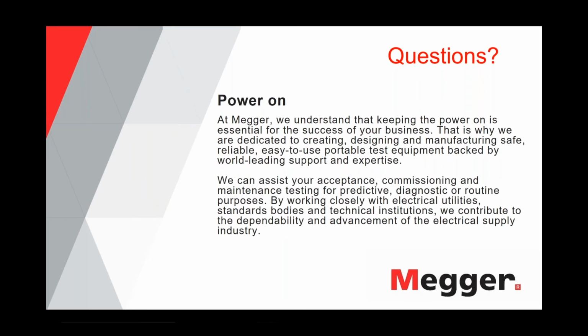So the state of the art approach in the industry today is that when you do a commissioning test, which means you have to do a voltage withstand test and you should do some diagnostics, it is the partial discharge test that people are after.